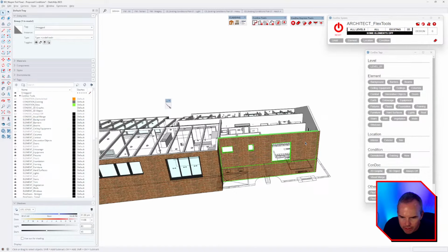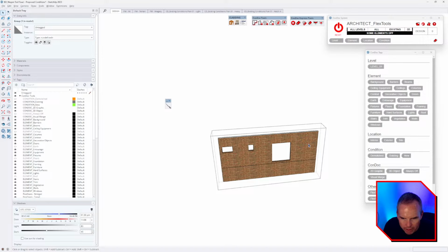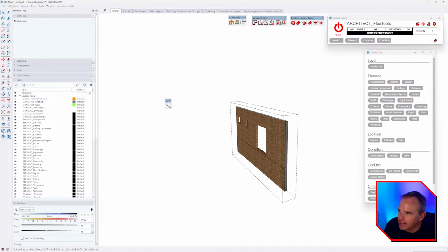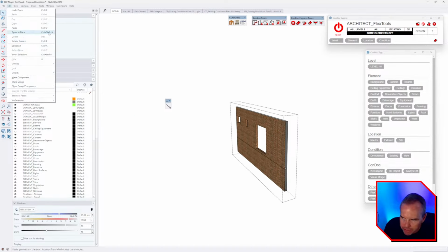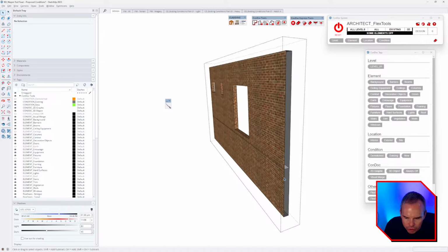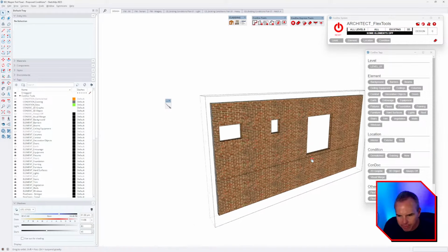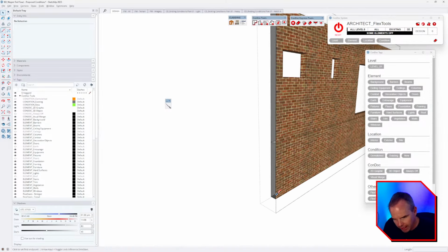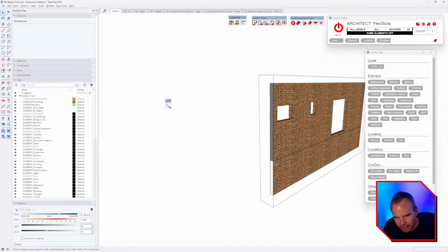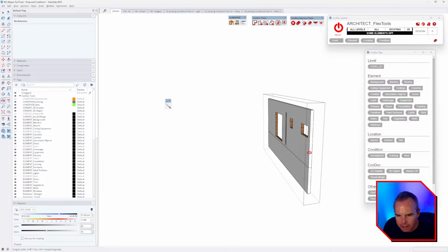All right, so that group, I pulled it out of there and then I pasted it back in place. That's under Edit, Paste in Place. My keyboard shortcut is Control-Shift-V. And then I'm going to use my line tool and patch that up. And we're going to patch this up as well, like that. Probably could have just drawn like that.